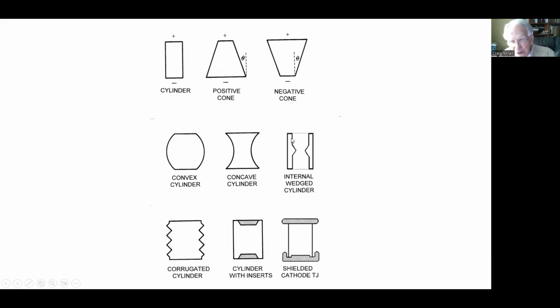In many applications of vacuum flashover, the vacuum is on the inside, what we call an internal cylinder, and the outside is typically insulated by solids, oil, or in some cases high pressure SF6. Normally, however, the flashover weak point is still the inside. Another very common one, which I did a fair amount of work with, is an inverted corrugated cylinder. In this case, the corrugations are on the inside.